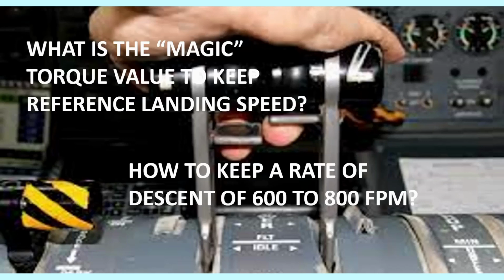which is a typical range for executing a non-precision or a precision approach. Somewhere around these values, 700 is what they call a very good one, the best one, but 600 to 800 feet per minute is what is recommended. Now this value normally is scanned from the vertical speed indicator. That's what we normally do to get the numerical value that we are following, but often it becomes a bit hard to actually pick that value, which sometimes is very small, or maybe the needle, and you are scanning other things and so many things are going on in the final approach.